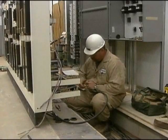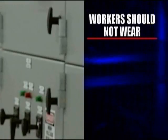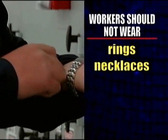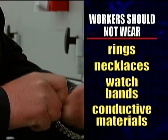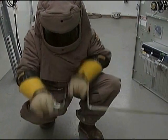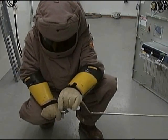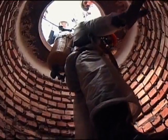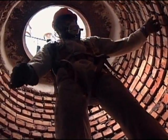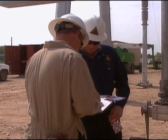Do not perform work in areas that are not illuminated sufficiently. Workers working around live parts should not wear jewelry such as rings, necklaces, watch bands, or other conductive materials. All tools and other conductive materials should be handled cautiously so that they cannot accidentally touch a live part. When working in confined spaces, other rules apply for exit and egress. Please contact your supervisor prior to entering a confined space.